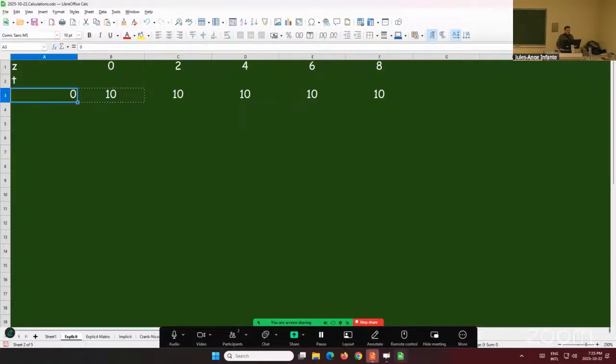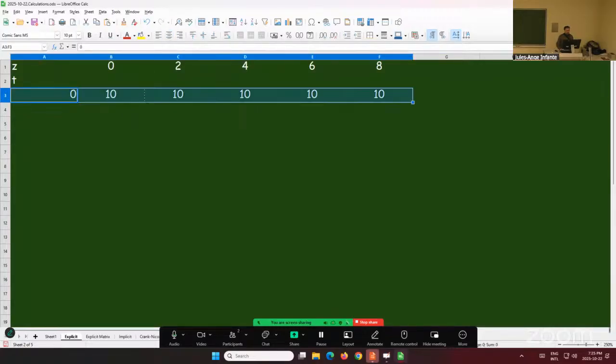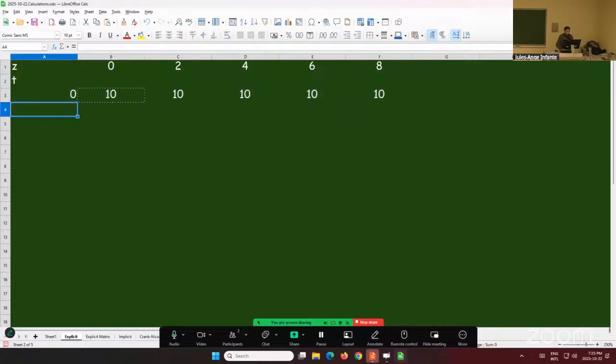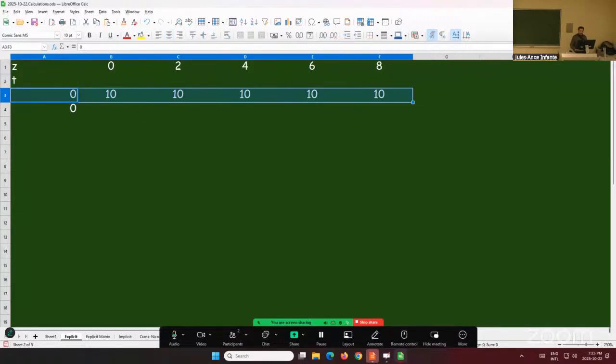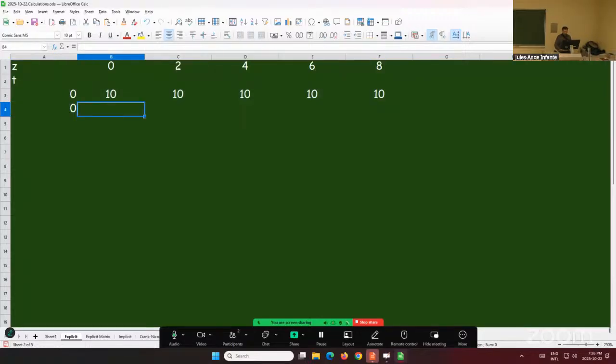Now, I should say, my real 0 will be after this, okay? So that's blanket, but at the boundaries, I have an instantaneous reaction, right? So I'm going to set my boundary conditions at the true 0 here. That's the time-dependent 0. This is an idealized 0, but really my boundary conditions are here. So I have instant dissipation of pore pressures at the boundaries.